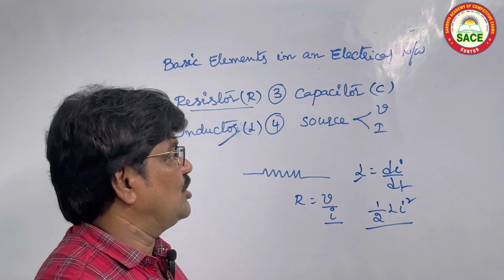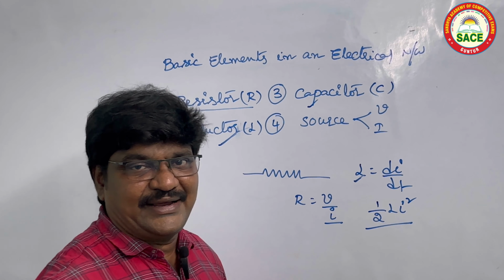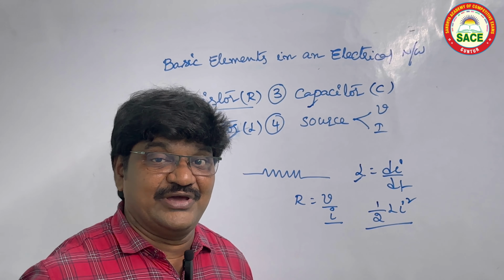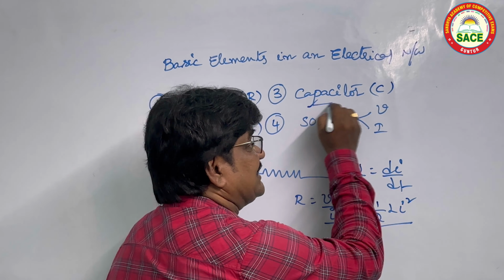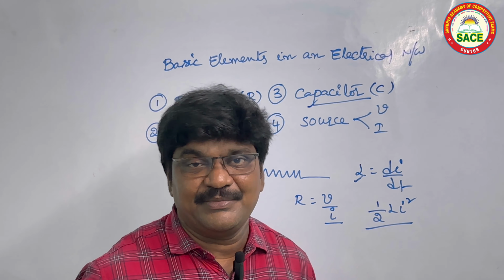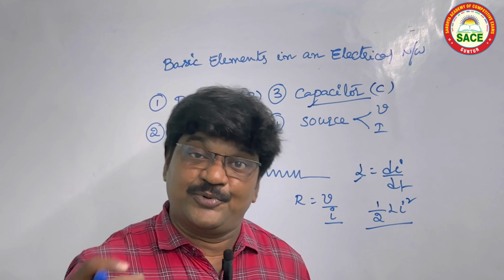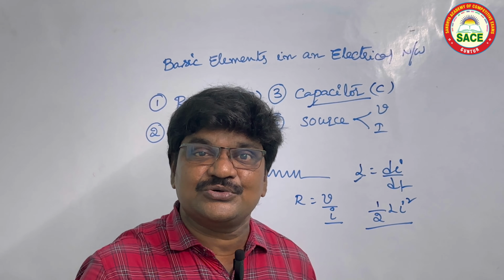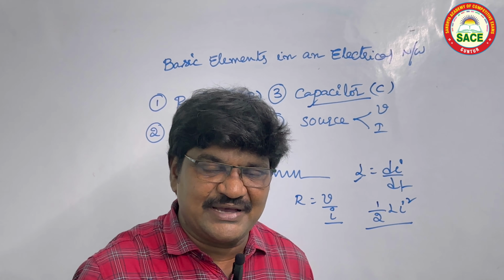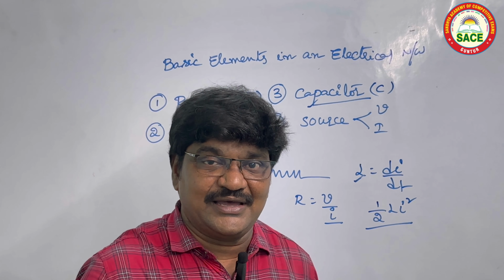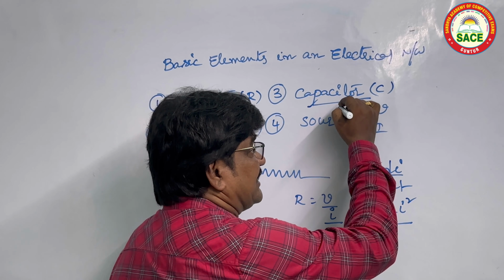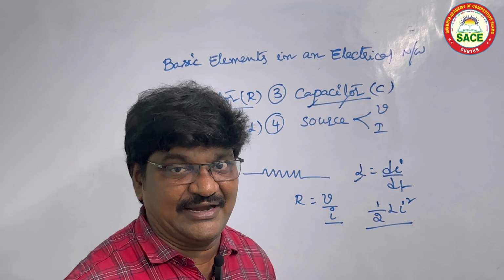Again one more thing is called capacitor. Right? What is the capacitor? Two conducting plates separated by a dielectric material is called capacitor. The property of a capacitor which stores electrical energy is called capacitance. So what is the capacitance's main role? It doesn't allow sudden change in voltage. Right? So that's why capacitor has the main role in our electrical circuits.